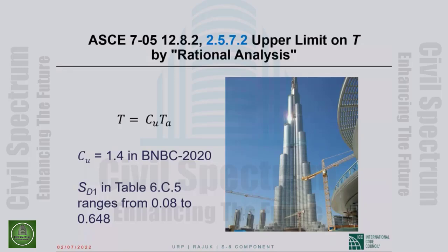You can compute it as long as you want it to be, but for design purposes, you shall not take it any more than a multiplier times the approximate period. So rationally computed period is tied to the approximate period. Actually in ASCE 7 seismic design or BNBC seismic design, you never get away from the approximate period.